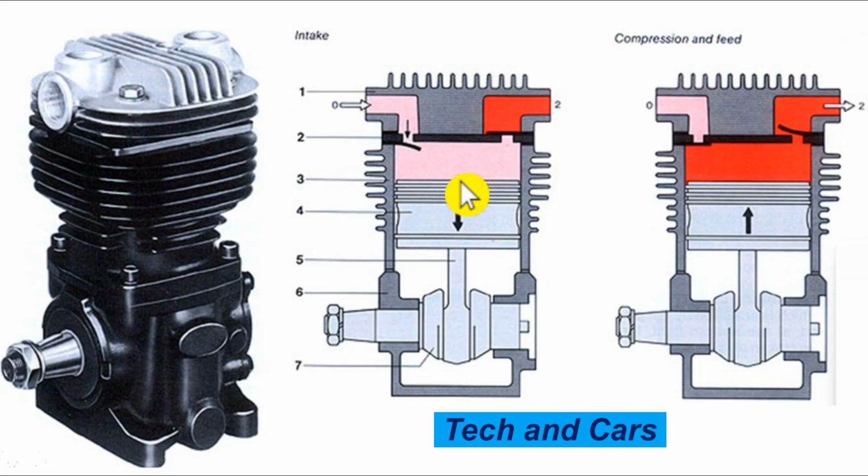A clogged air compressor breather tube can also be a culprit. The crankshaft cannot vent properly. It will force oil past the piston rings into the compression chamber as well.